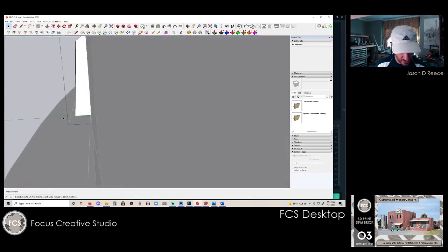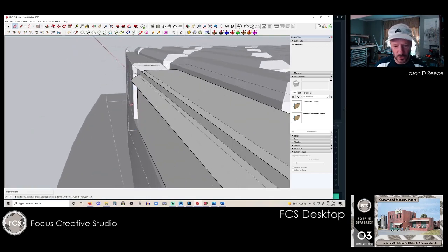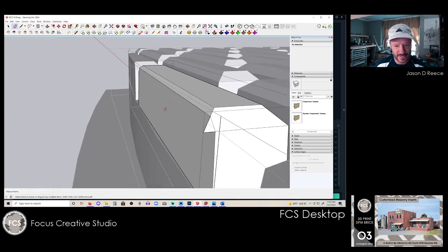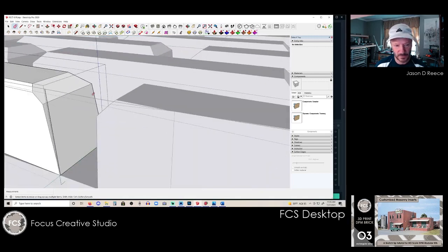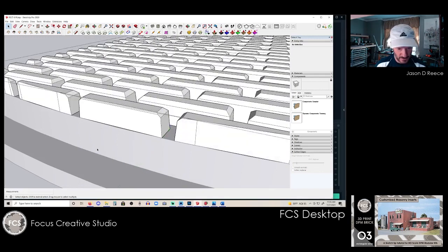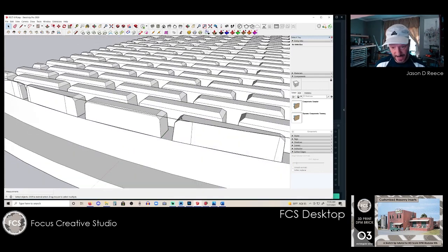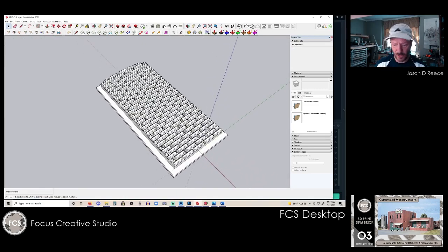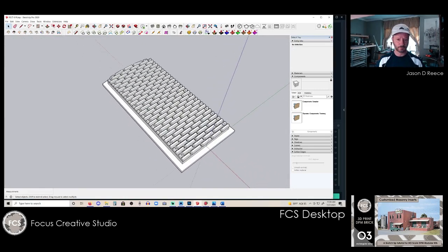So all that's selected, edit, intersect faces with selection. Now I come in. I'm going to use the eraser tool. Get rid of this outside. Again, we didn't follow the precise geometry of the segments. Not needed up top. Don't make things harder on yourself. Enough hurdles we gotta jump through sometimes to make this work. So that geometry is clean, done. Get out of that. Escape, get out of that. Now I can delete this. Delete. Now you are set with a base brick file insert for the rectangular series for the DPM modular pieces in HO scale. That's it. That's all it takes to get there.